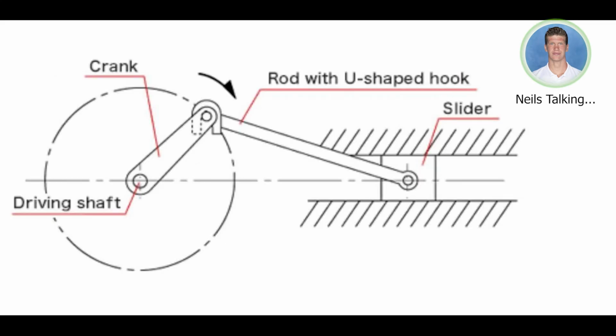The last concept that we came up with is the crank and slider mechanism, which uses a motor at the center of the crank for rotational motion. The crank is linked to a rod at the end of the limit of the diameter on the crank. The rod is connected to a slider that moves vertically, in our case, as the TV needs to move up and down on the vertical axis.